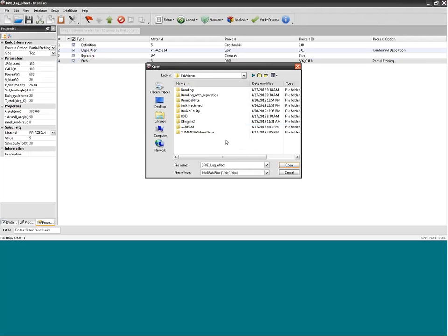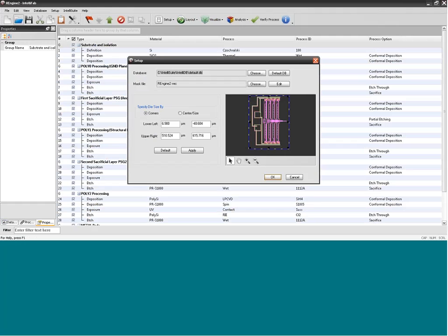These are standard processes like maybe the MEMS process from MEMSCAP or the Summit process from Sandia, the Screen process out of Cornell, or we've got, say, the Texas Instruments micromirror array. A lot of the standard processes are included within IntelliSuite, and within those processes, you'll see this example is an example of the MEMS process.